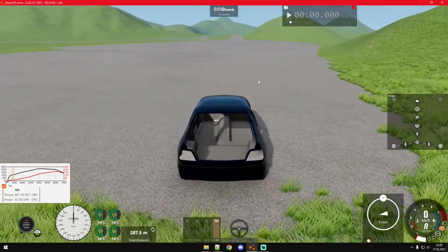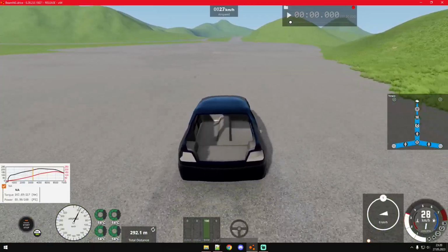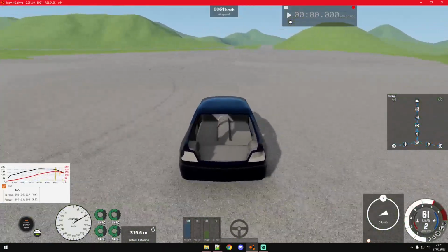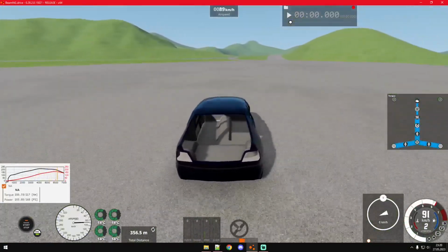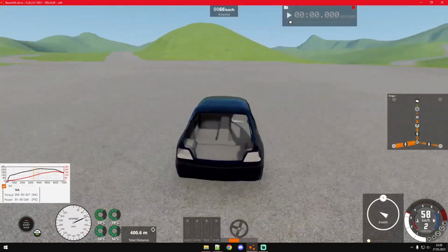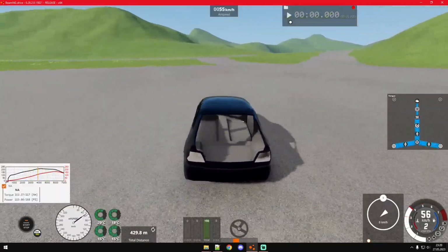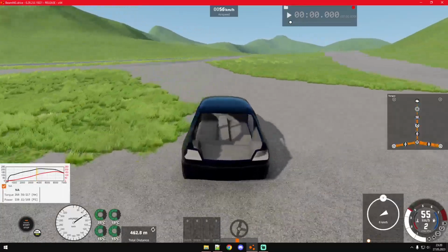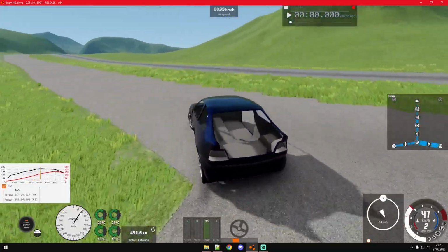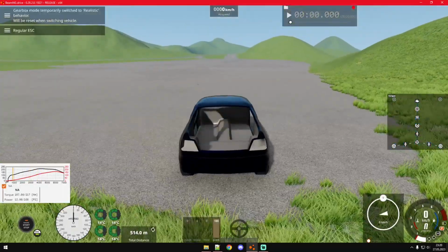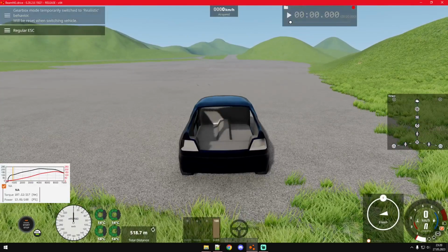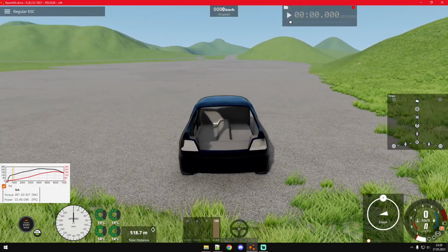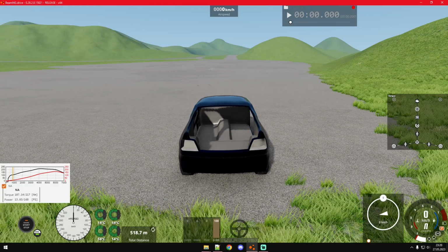So the difference between what yaw rate you would have when taking a normal corner and the one you're having at the moment. If we are just taking this corner like usual, we don't have a difference between what we would expect as a yaw rate and what we're actually getting, and then the stability control won't act.